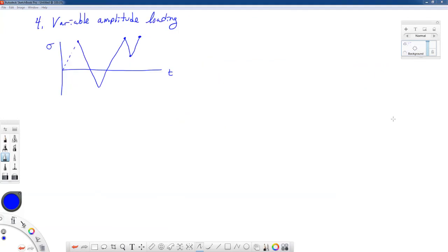All right, to illustrate what goes on with variable amplitude loading, I think it's probably best if we start with a few examples. Now, for our purposes right now, I am always going to start at a very high level where I have exceeded the yield stress of the material, and I'll always end at that very high level. And we'll talk about why I want to do that later. But here's a very simple variable amplitude history. Here's one complete cycle right here, and there's another smaller cycle. So let's plot the hysteresis response for this.